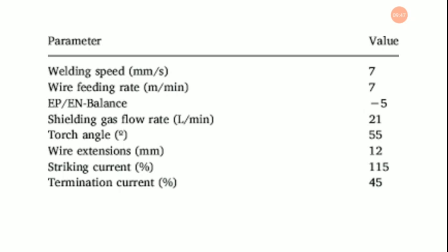This is because at low IP up to 200 ampere, the heat input is less and it is not sufficient to melt base metal with the filler material. The peak current more than 200 ampere gives more heat and it melts the base metal with filler material completely and gives full penetration. So peak current plays an important role in the determination of penetration value.